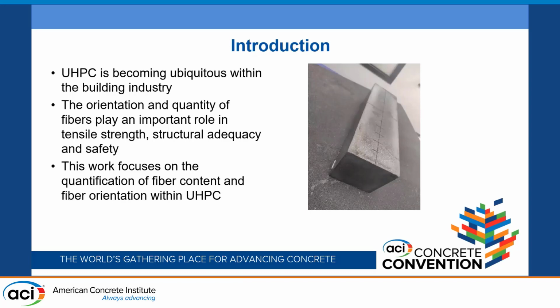There are obviously some benefits to aligned fibers in tensile specimens and tensile structural components as well. And so this work focuses on quantification of fibers and also alignment of fibers within UHPC. The next question might be, well, can this work with FRC without UHPC? The answer is there are applications to that, but we have not gone down that road. And as we talk about materials that attenuate, that could be a potential issue.